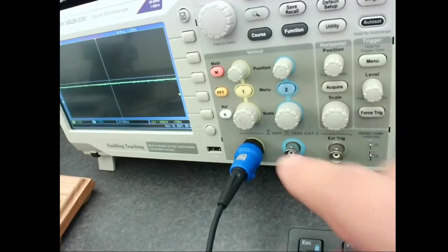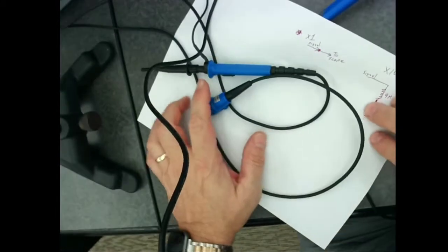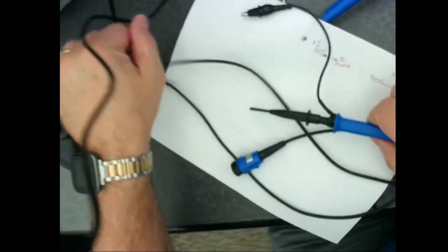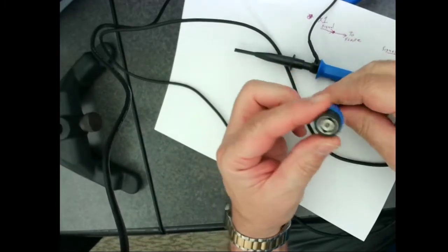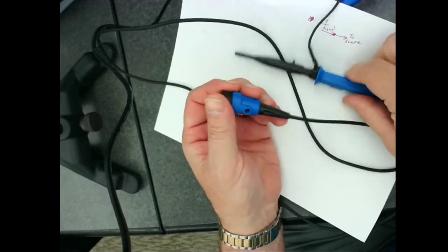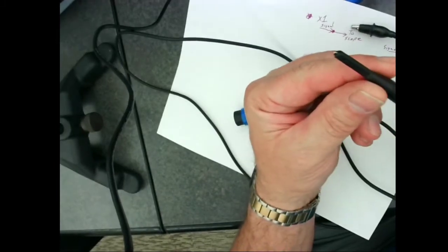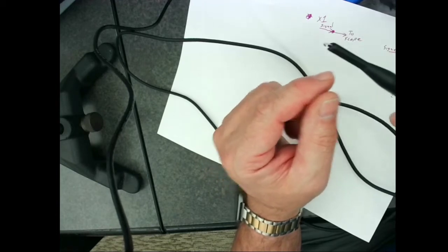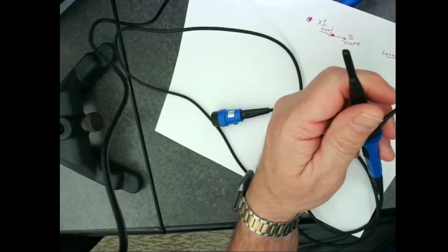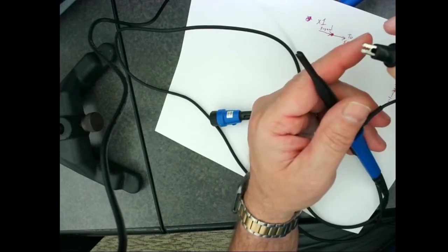So one of the first things we have to do, of course, is select our probe. So let me talk about the probe here. When you get an oscilloscope, usually it'll come with an official probe. It has a coaxial type connection, and then there's usually a little pinch connector on here, so you can clip it onto a wire and capture the signal. And then there's a little alligator clip for ground.